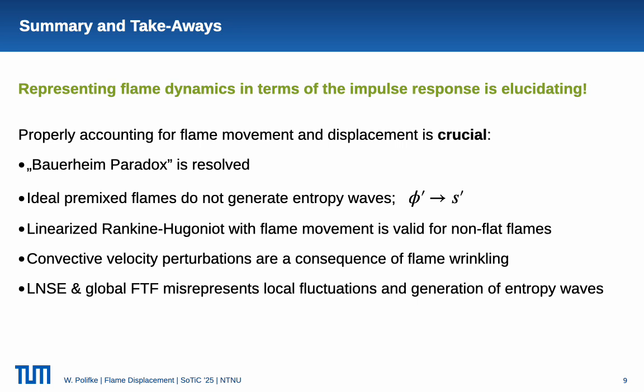We have some additional evidence that convective velocity perturbations are a consequence of flame wrinkling and not of immediate acoustic to hydrodynamic mode conversion. And unfortunately, LNSE combined with a global FTF misrepresents local fluctuations of heat release rate and the generation of entropy waves.